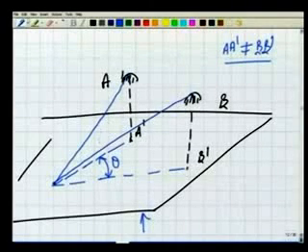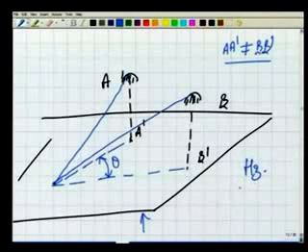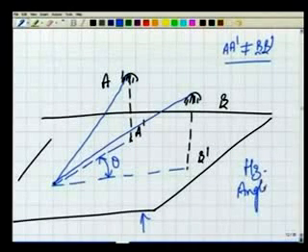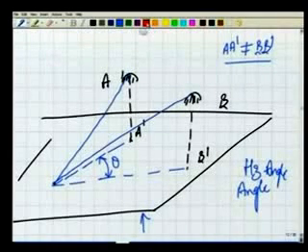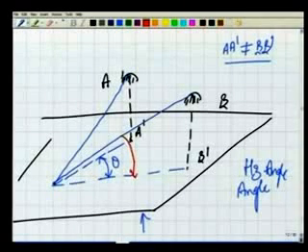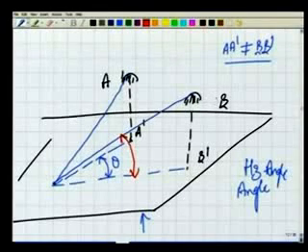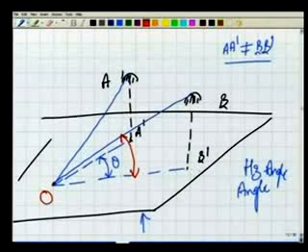Well, how about the vertical angle? This is about the horizontal angle or simply angle. What is the vertical angle? The vertical angle, as you can guess easily, is the angle in the vertical plane from the horizontal line. So for object B, at this point where the observer is, the vertical angle is BOB dash.